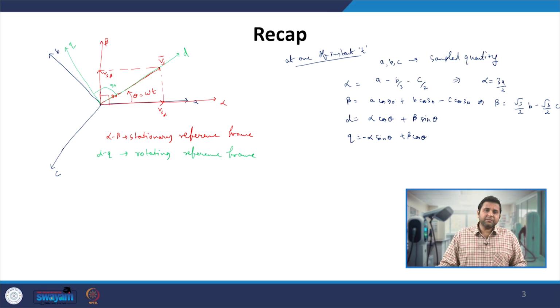And there we have seen that since the space vector is rotating in a 2-dimensional space, we need to provide representative axes, and those should be 90° apart from each other. If they are 90° apart, then we can ensure that the components of the space vector on those axes are independent of each other, and we can change those axis components, and a change in one component will not have any impact on the other.